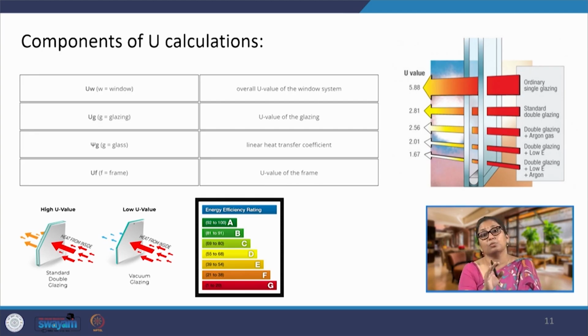We can use whole building simulation tools. What we do when we are going ahead for green building certification is that we create a simulation model, a hypothetical model with the given input information of the building, and calculate the energy that is going to be required to run the building. And then we will have the solutions, the strategies, the choices of materials, of design, and we will try to reduce the energy which is going to be consumed by the building.